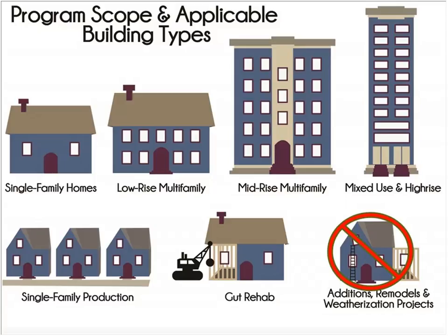As you know, existing homes are a huge area. We need to make improvements to our millions of existing homes that are wasting energy and poisoning their occupants. But it does require a full gut rehab, and so it's very important that the energy rater can see an exposed thermal envelope, either on the interior or exterior, to make sure it was done right. They also have to see behind the shower and tub surround to make sure there's non-paper-faced drywall back there that won't mold.